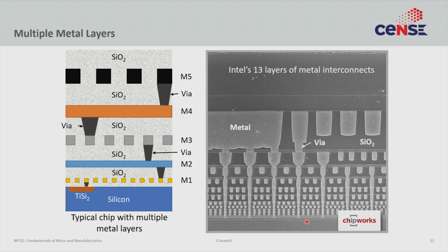Now, each of these metal layers must be insulated from each other, otherwise the signals will cross, and that insulator must be of the lowest dielectric possible. Otherwise, from the capacitance formula, you know, if there are two metal layers and you have an oxide in the middle, then there would be a capacitance, right. So, you do not want that capacitance because that causes delay. So, you want the epsilon to be as small as possible. Now, the best thing would be if all of this insulator was just air, but in practical devices that tends to be hard. There would be mechanical problems of having an overhanging metal. So, what we do is we fill it with silicon dioxide, all right.